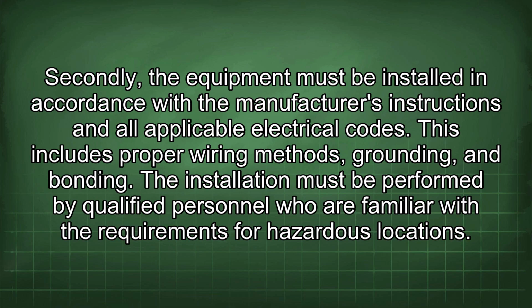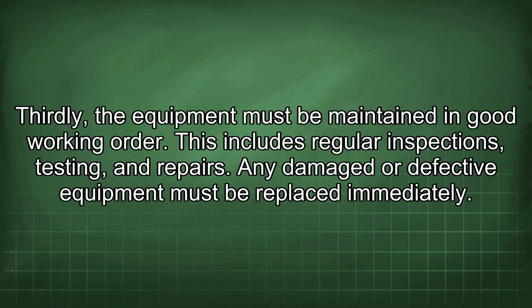Secondly, the equipment must be installed in accordance with the manufacturer's instructions and all applicable electrical codes. This includes proper wiring methods, grounding, and bonding. The installation must be performed by qualified personnel who are familiar with the requirements for hazardous locations. Thirdly, the equipment must be maintained in good working order. This includes regular inspections, testing, and repairs. Any damaged or defective equipment must be replaced immediately.